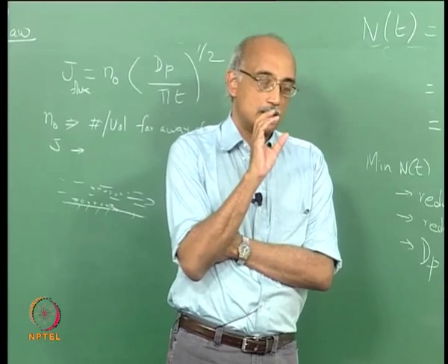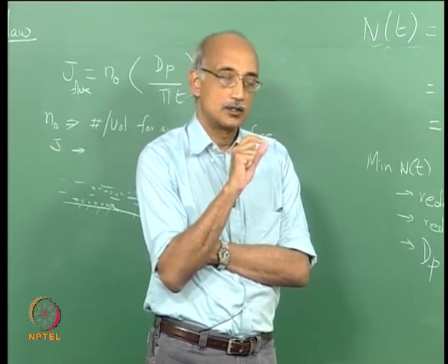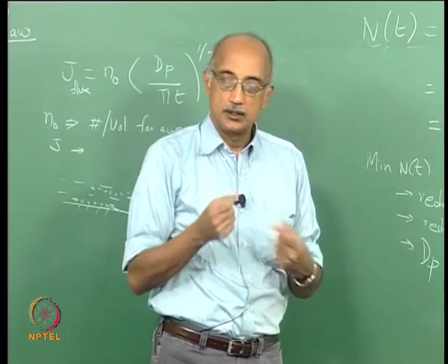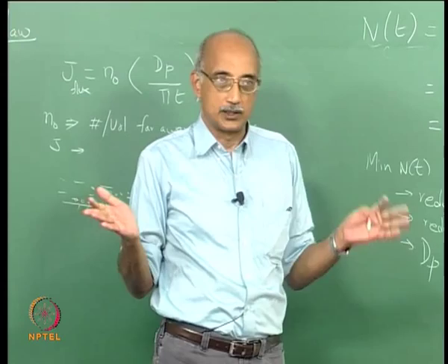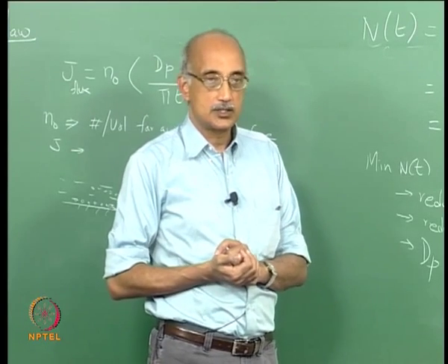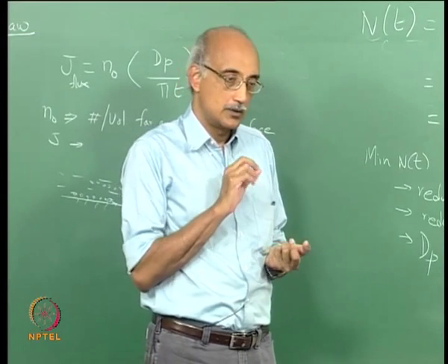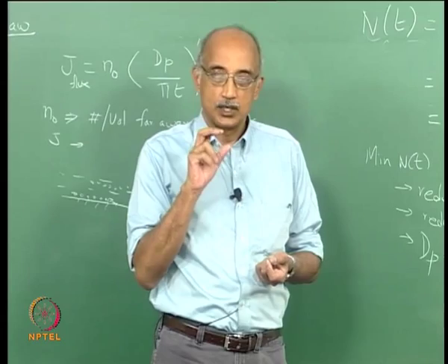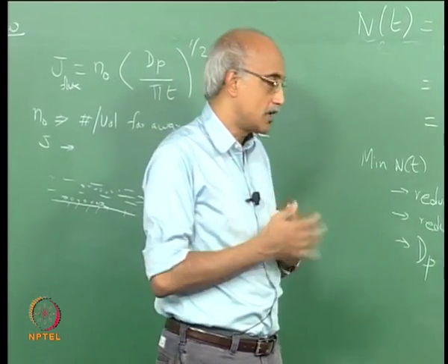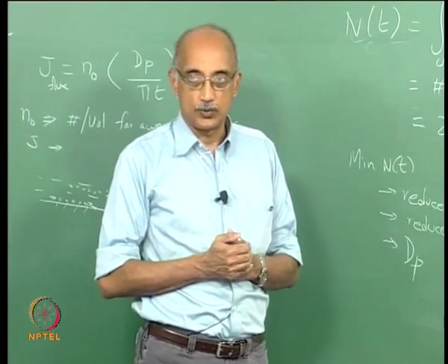You have to understand, is your product sensitive to particles, and if so, what is the size range of particles that it is most sensitive to? And the way you try to control the transport mechanisms present in your system is by adopting an appropriate strategy. You cannot minimize everything. Well, you can, but it's going to cost you so much, your product becomes economically unviable, right? So you have to have a practical strategy. You don't try to get to 0 particles in your product, but you try to have an optimum control strategy where you identify the most sensitive particle sizes and have the maximum containment in those size ranges, and for the less sensitive size ranges you don't worry about it so much. So it's a combination of strategies that you need to evolve by keeping in mind a holistic picture of what your product requirements are.